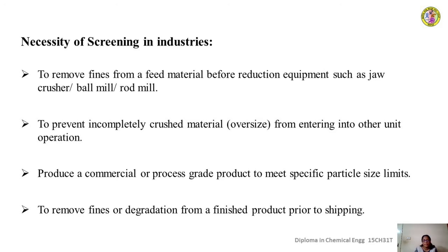Otherwise, the material that has already undergone size reduction also enters the size reduction machine, and its performance, meaning the capacity, gets reduced. So to remove the fines from the feed that is to be fed to a size reduction machine, screening is done. That is, the material before it is fed to a crusher or a grinder is to be separated out of all the fine particles that may be present. That is one need.